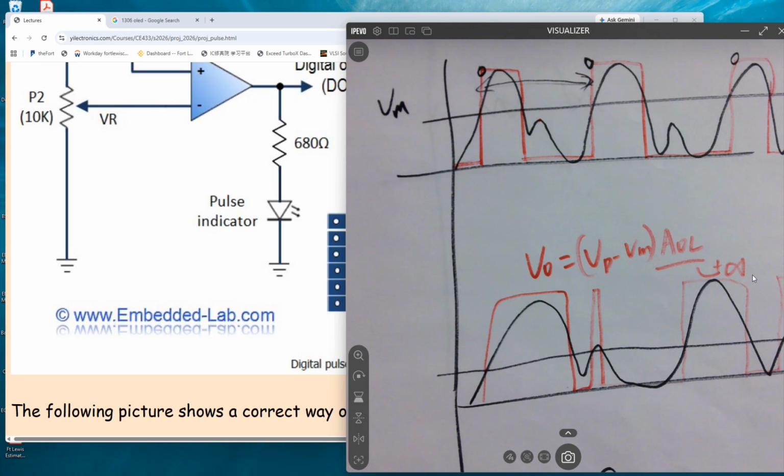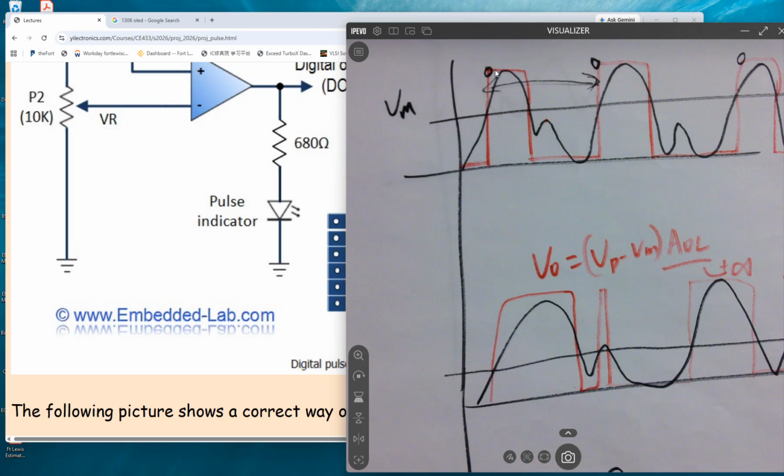It became super useful during COVID or any of the, what's that called, outbreaks of diseases. And so in that case, you have to use 2 colors of LEDs. Usually, I forgot the colors, but for example, blue and red, right? And then you detect the voltage levels over here, and you calculate the ratio of the two colors to find out how much oxygen is being taken into your blood, the red blood cells. That characterizes the functionality of your lung and becomes a very important vital of your body.